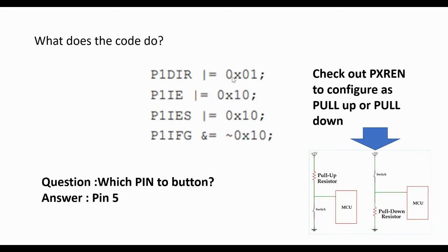Now, what if you configure this as 0x00? Obviously, it will not work. The LED will not work. Some questions could be designed in such a way that the value is changed to 0x00. Then they will ask you, hey, why is the LED not blinking? You have to troubleshoot. So the question is always referring to troubleshooting. That's why lab sessions are very important. Don't play around with the lab sessions. Sincerely do it yourself.